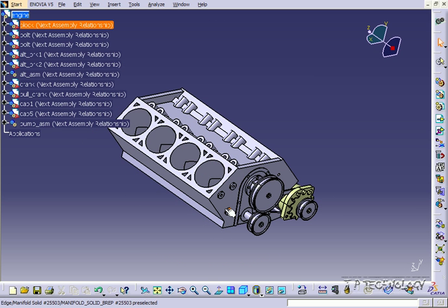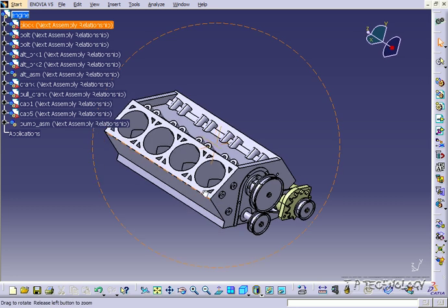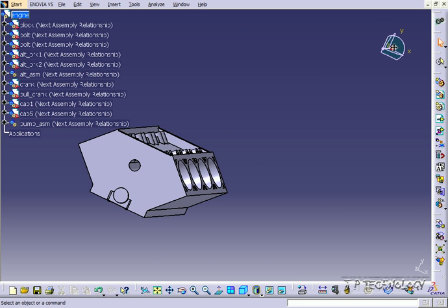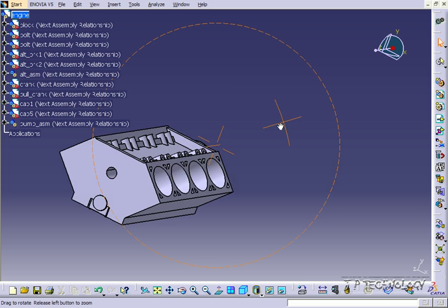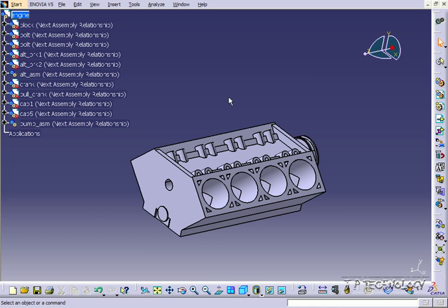And again, I can't emphasize exactly how important this is, because if I didn't have an axis there, when you try to throw it in there, you're going to get different results every time. And to be precise and consistent every time, create the axis that you want to rotate about. You can use an edge too, but if you want to rotate through, say, a circle, get that center circle's axis in there and rotate about that.